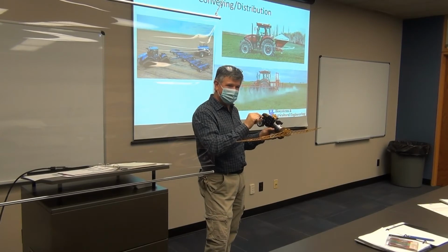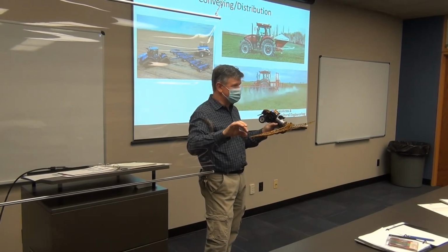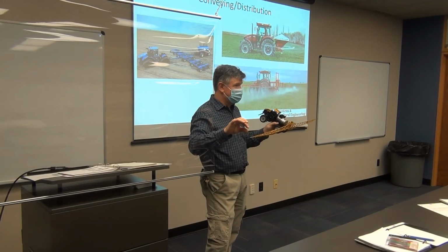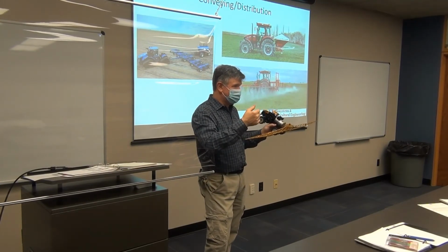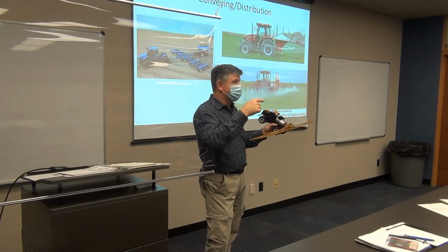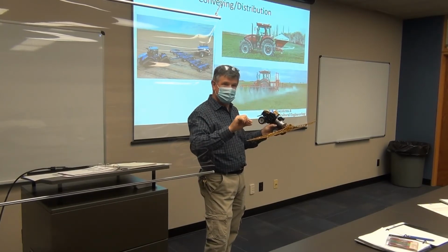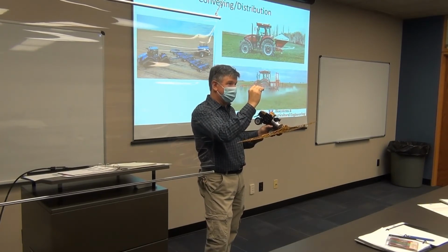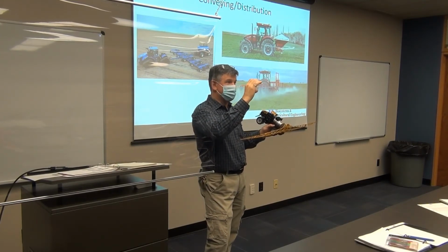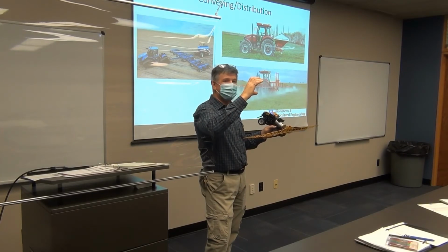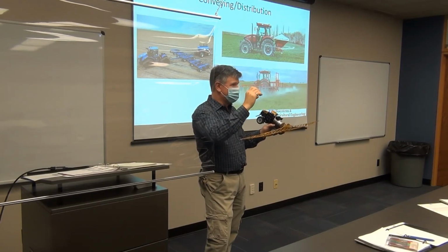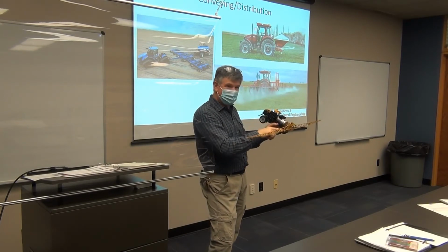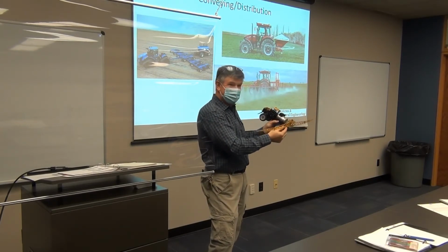Keep going, keep digging. So, Landon, you said, okay, the pressure's going to be different out here. Why is the pressure lower out here? Because of the distance. It's the distance, but go a little bit deeper. There'll be more friction in a pipe, right? How do I reduce the friction losses in a pipe? Make the pipe bigger. Oh, so could I adjust diameters of hoses or lengths of hoses?